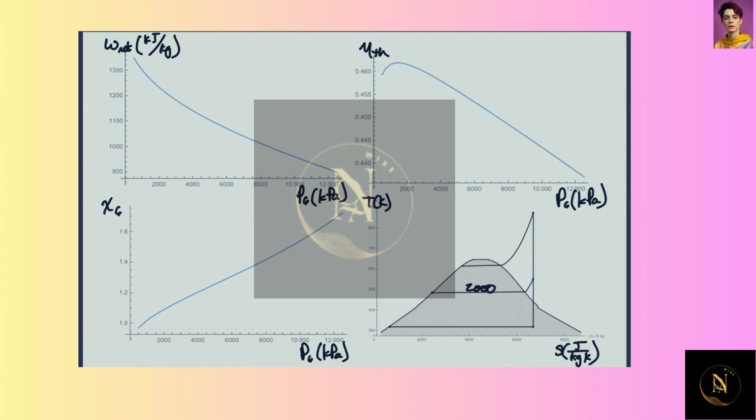So we're bleeding off, taking this at a certain pressure, and then coming out here to essentially help with getting the feedwater temperature up by mixing things here.